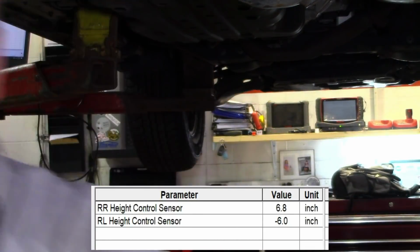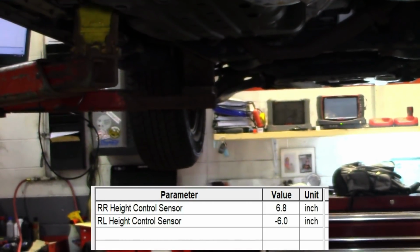So now we can compare the 2. This right height sensor didn't seem to have much adjustment, so I'm going to check it with the scope, make sure I have my 5 volts, my ground, and a good signal coming out of it. But actually, you know what?